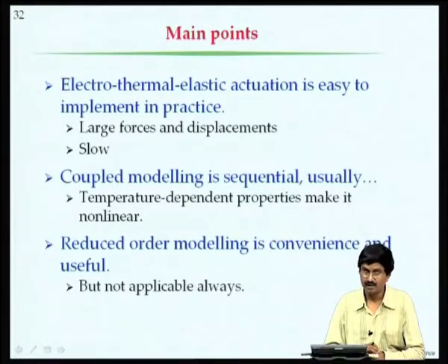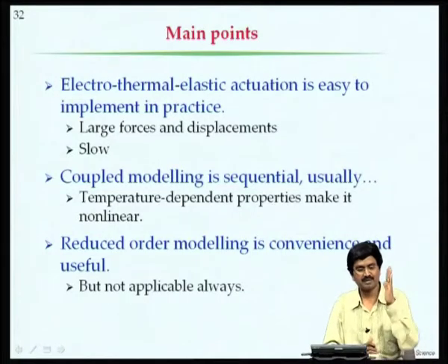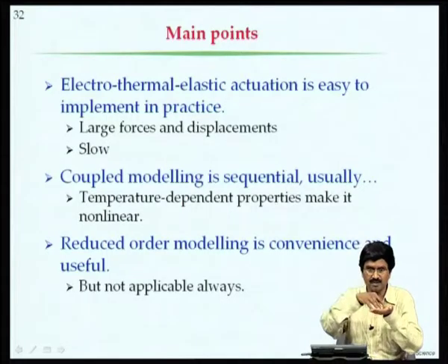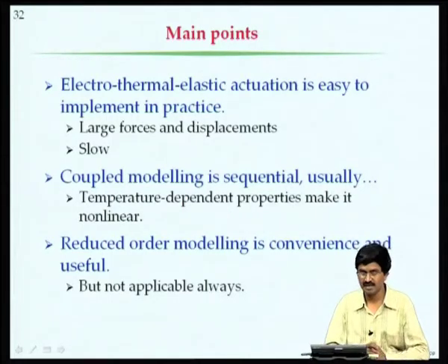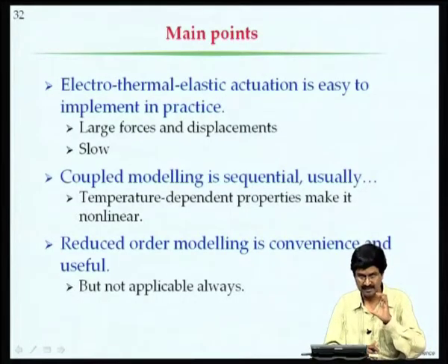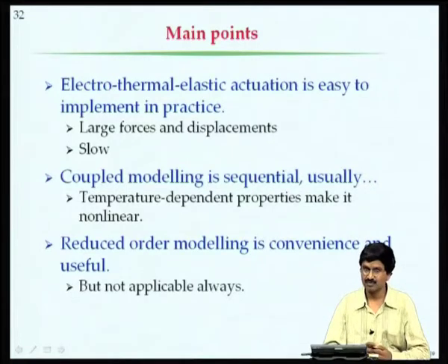There is a lot to be modeled there to get the heat transfer coefficient properly, because as we said just a few minutes ago, if you go to handbooks on heat transfer, they will give you the heat transfer coefficient for a vertical plate heated from this side or a horizontal plate heated from bottom or above, and all these different conditions, and are usually natural convection, meaning that there is no fan to increase the convective heat transfer. So, once we get those coefficients properly, and there will be scaling effects also, we need to take that into account and then solve the problem.